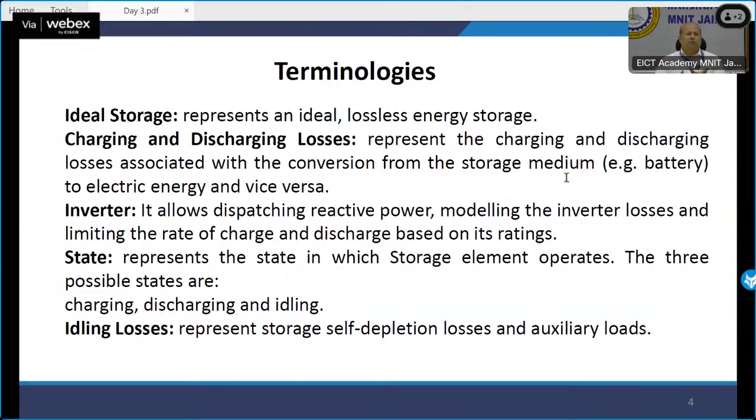But what we people do normally, we use it at 85%, we put it in charging, make it 95, again use it, 86, again put it 94. So 70 to 95, we keep on playing, keeping the mobile always fully charged. That's not a good practice. So what we need to do is allow the battery to discharge as close as possible, at least to the 20% level.